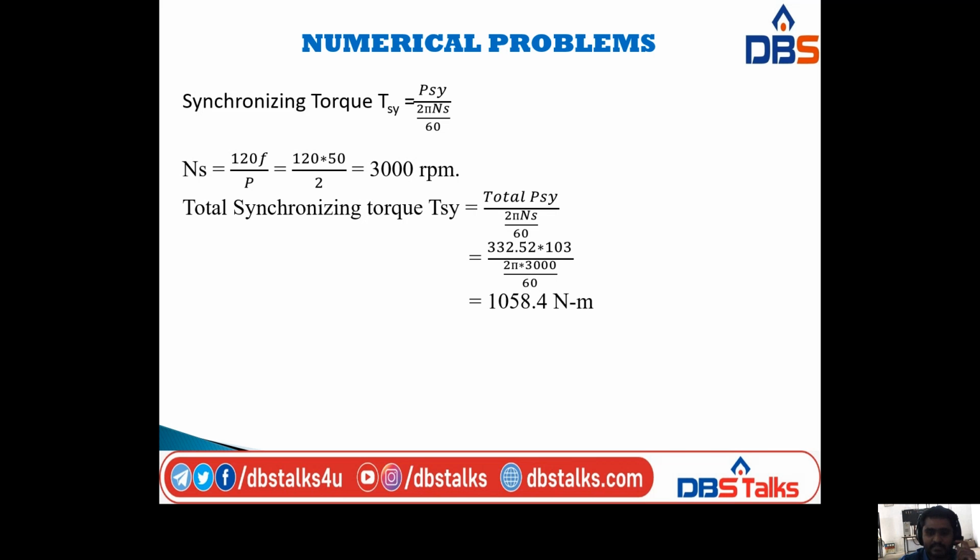In the problem they have already given the frequency, that is 50. So substitute here: 120 into frequency 50 divided by P, the number of poles. In the problem they have already given the number of poles as 2. So substituting, finally we have the synchronous speed, that is 3000 rpm.